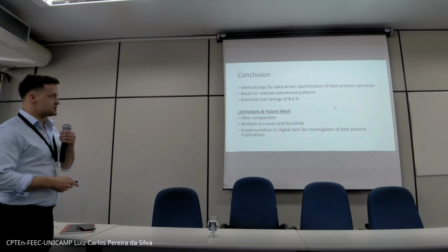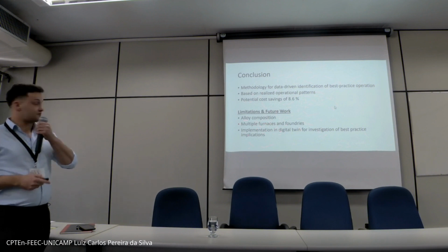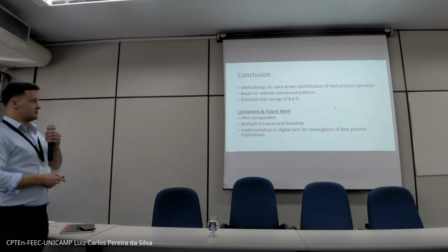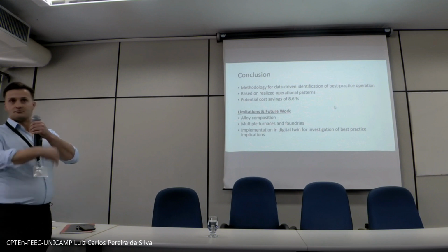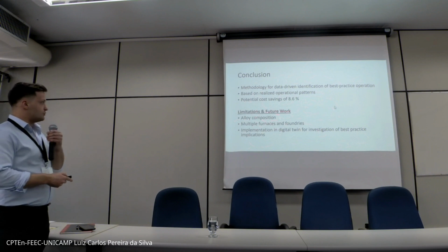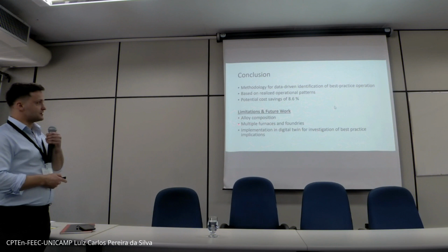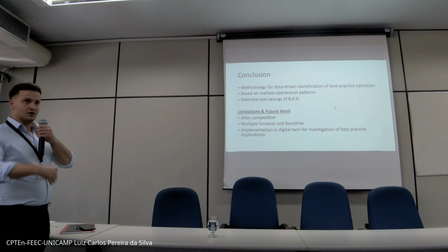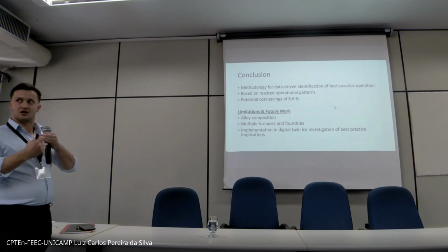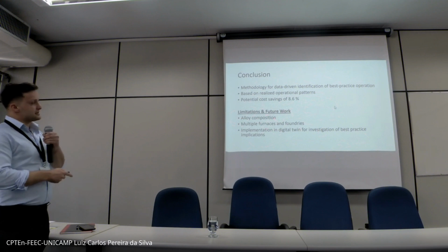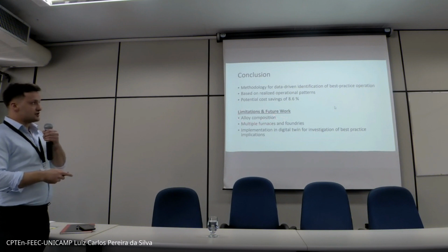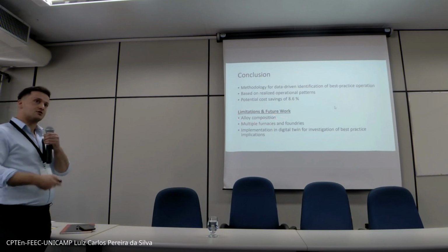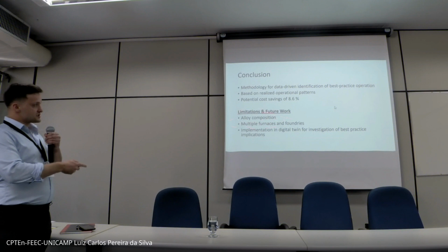Some of the limitations and future work that could be considered is that currently we consider all melts the same, but we have different alloys in our furnace. Every time we start a furnace, we will have a different alloy composition that we are trying to hit. In this case, you could try to do a best practice operation of induction furnace melting based on alloy composition.